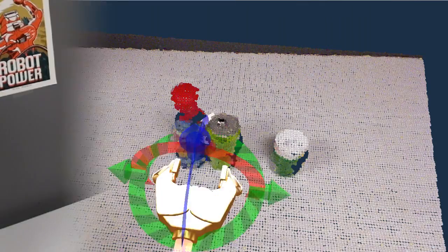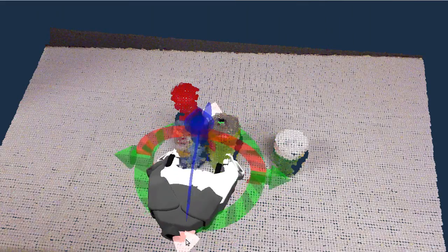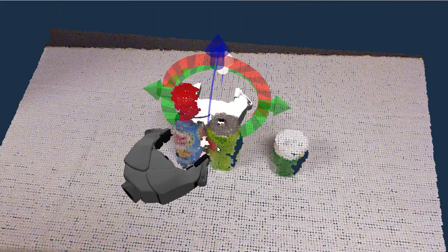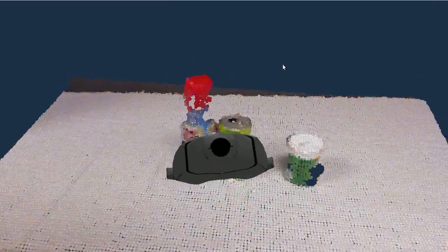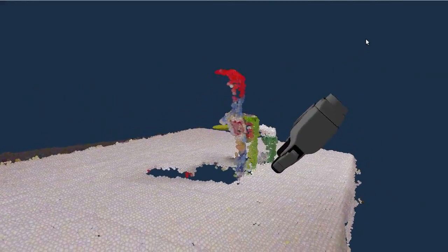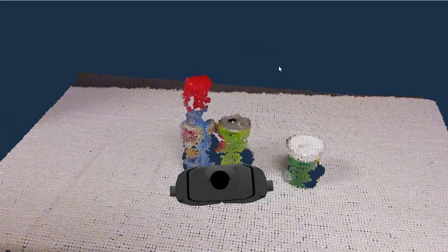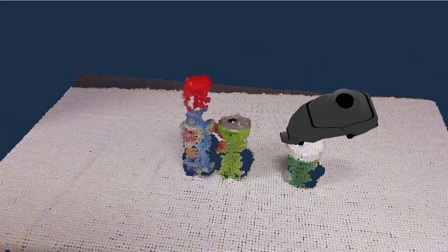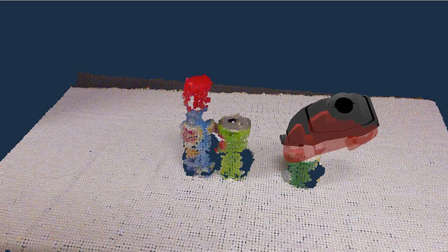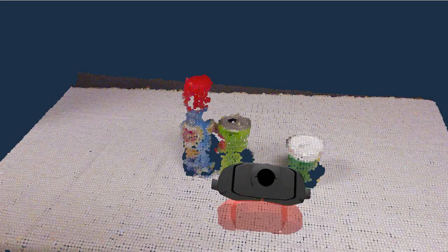We have implemented a collision constraint algorithm that prevents the user from selecting a grasp pose that is in collision with the environment. Information about unfamiliar remote environments is usually limited to noisy and incomplete sensor data, often in the form of 3D points. Our algorithm can render six-dimensional interaction of a rigid object model, such as a robot gripper,